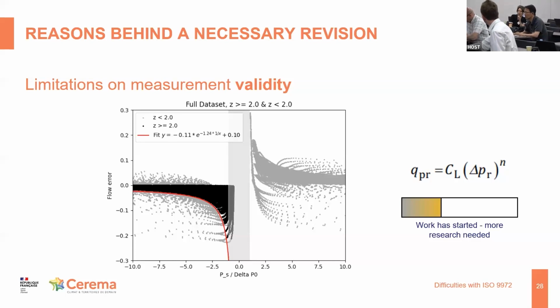So this is the mathematical error due to the ratio between pressure station and zero flow pressure, no matter where the zero flow pressure comes from. And it would allow to include the error due to the zero flow pressure in an uncertainty calculation instead of just setting an arbitrary limit of 5 Pascal or something.